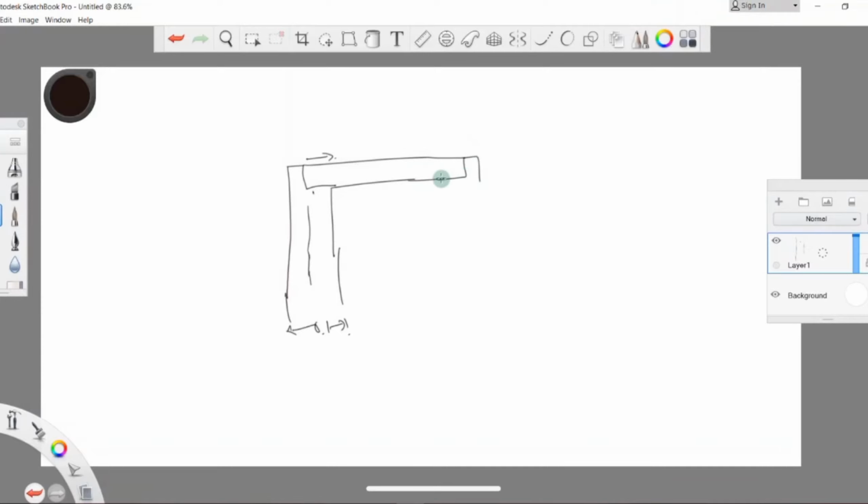and also in this case we got the beam and we got the column like this, and this face at the face and this portion at the face of the column. To do this, the beam has to offset by half of the width of the column, that is 50 mm. Okay, because this entire width is 100 mm or 0.1 meters. Similarly, here we will go in the negative x direction of 50 mm by 50 mm. Okay, all right, so as x is positive in this direction, so this value is positive and this value is negative.